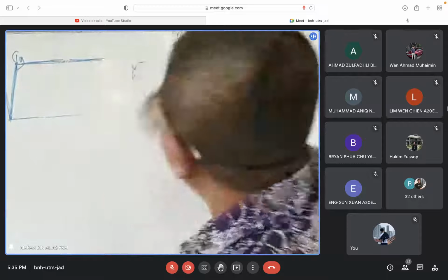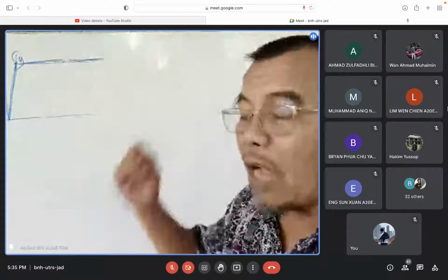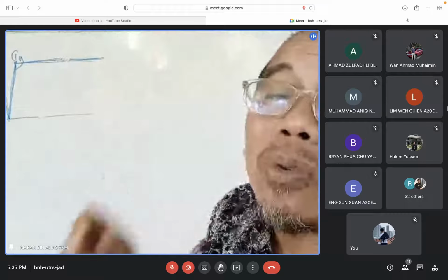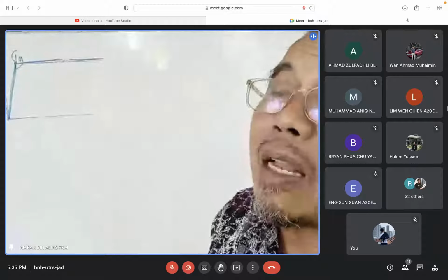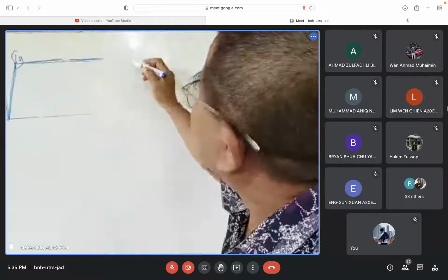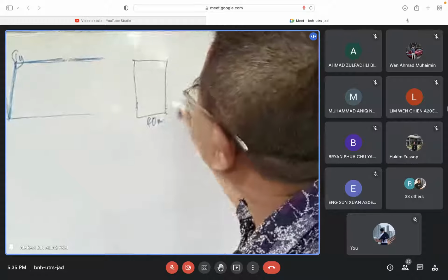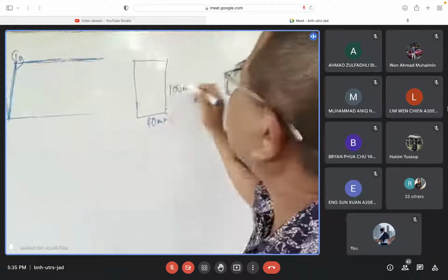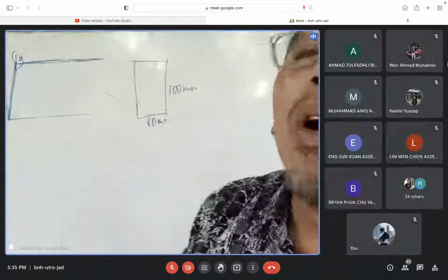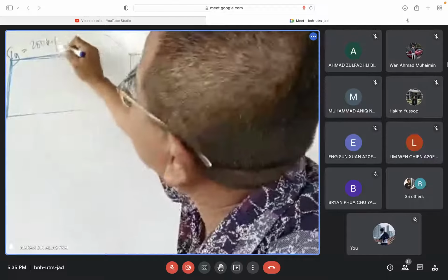And then how to calculate that force, how much force we want to push. Before we calculate the force, we have to calculate the moment required. What is the moment required? So, let's say the cross section of the beam is like this, 40 mm times 100 mm. So this is the beam cross section. The beam has a material like this: the sigma y is 200 megapascal.